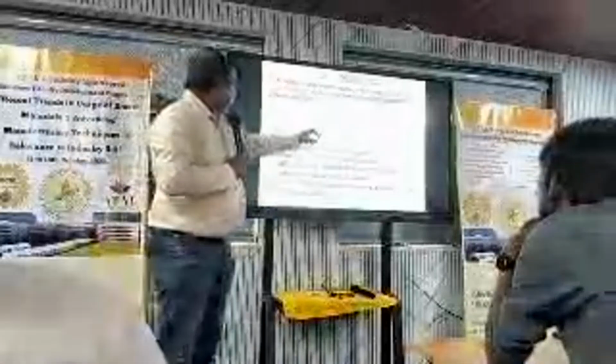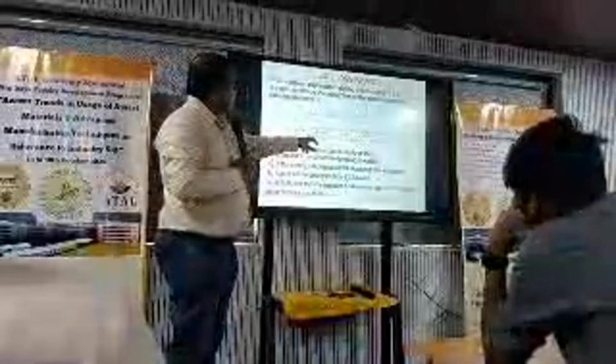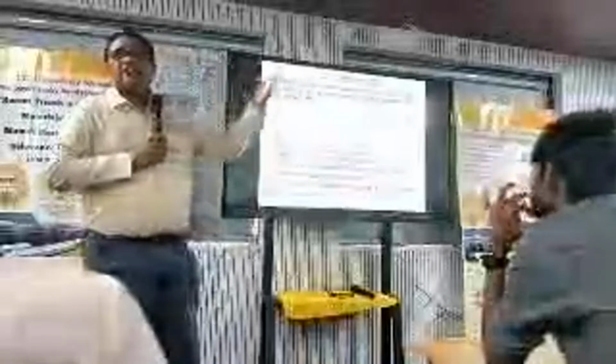E1 is the Young's modulus of the bottom material, and E2 is the Young's modulus of the viscoelastic material. H1 and H2 are the thicknesses of the materials, like the bottom layer thickness and the viscoelastic layer thickness. So the system loss factor mainly depends upon the Young's modulus ratio and the thickness ratio. So we have to design the material accordingly, and we have to find the higher loss factor. If it is a higher loss factor, then more vibration energy we can reduce. That is the equation.